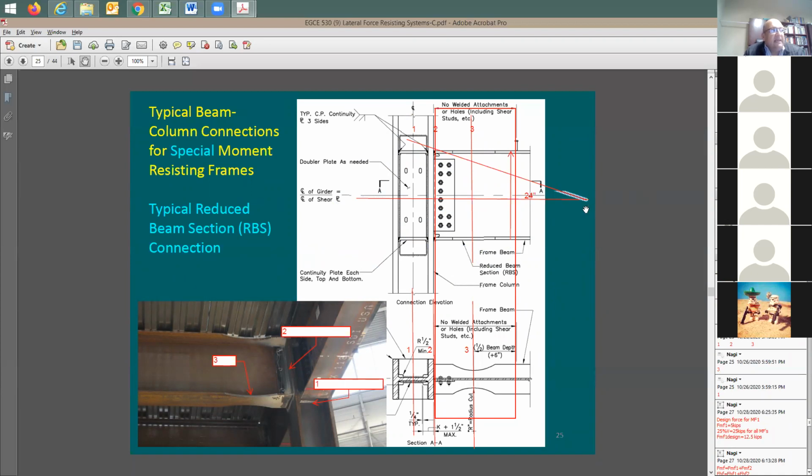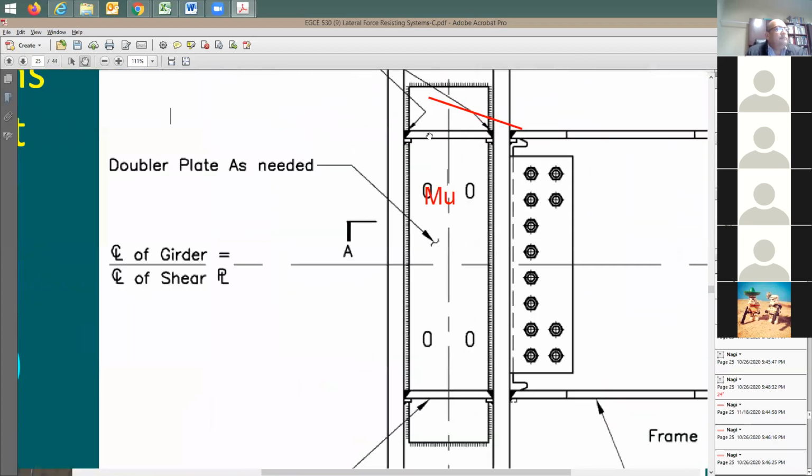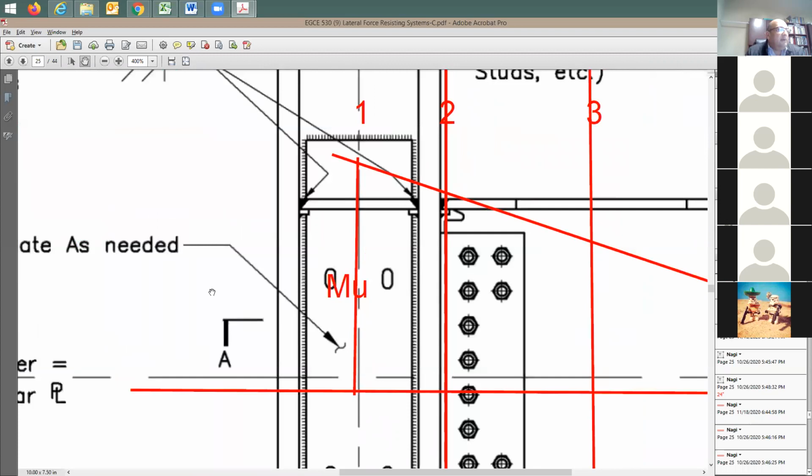So this is actually what you're going to be reading off your moment diagram when you do the seismic analysis. This gives you the moment value, this moment ordinate that you're going to be reading, and this gives you the moment at the center of the column. So once you run, let's say, a SAP model, right? This gives you M ultimate at the column that you're going to be reading. I'm going to say here M ultimate at the column, which is this value here. This value, in reality, you don't really need it. I mean, you don't really need this value here.